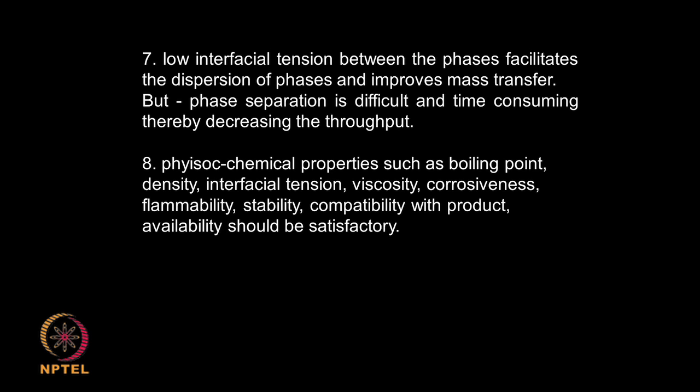So, if the interfacial tension is low, you get good dispersion, you get good mass transfer, but later on the settling of the heavy with the light becomes a time consuming process. Okay. And then other physicochemical properties such as boiling point, density, interfacial tension, viscosity, how corrosive it is, is it flammable, is it toxic, is it safe to handle, all those factors are also considered when you decide on a solvent.